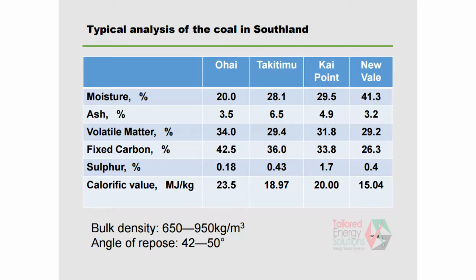Okay, the angle of repose, just be aware, for coal is in that range, not much change. This is why the hoppers were designed to a 60-degree angle. That's the angle of repose.